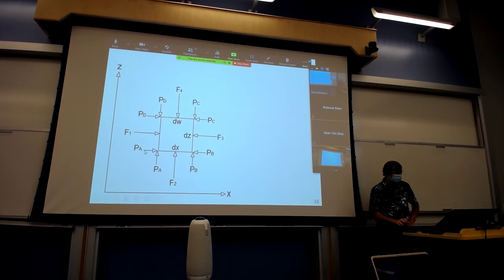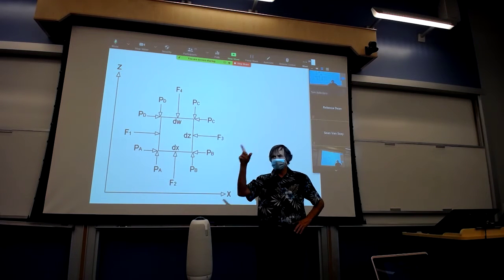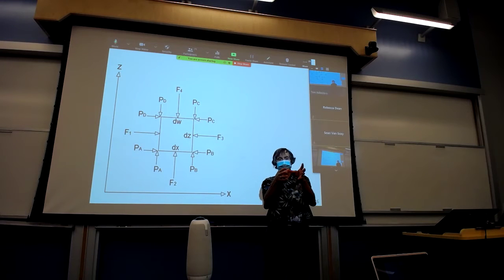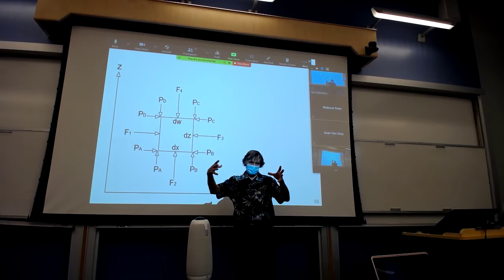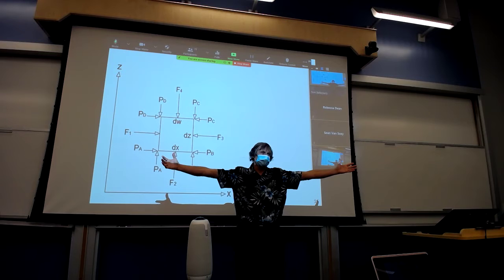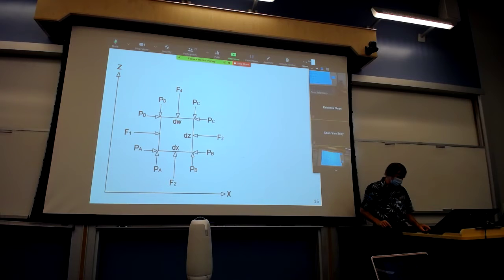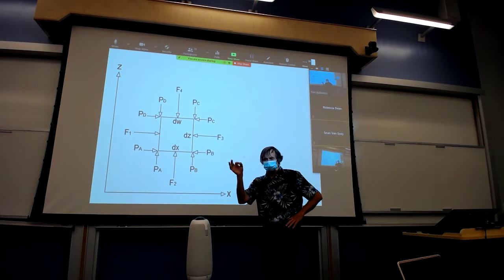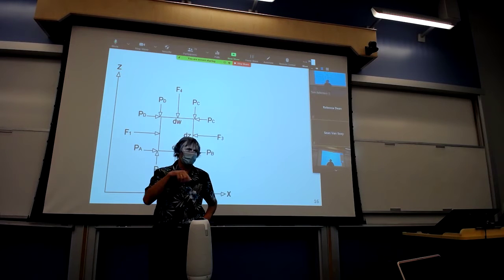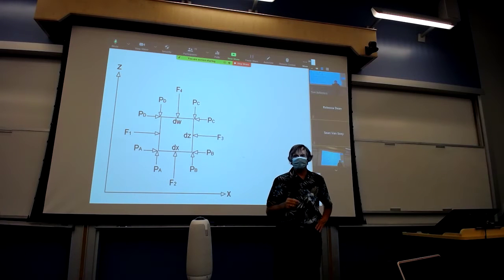Then in this little cube, now a 2D element, we assumed that pressure varied over the outside of this. Again, that represents the fact that we took this little cube and removed it from the fluid, and these pressures acting on the outside represent the rest of the fluid that's really out there. We assumed that pressure was varying as you move through the system. So if we moved from the lower left hand corner, A, to B, we had a change in pressure from PA to PB. Pressure is a scalar quantity. That means that it operates the same in all directions at a point. When we integrate pressure over an area, we get a vector, and that's a force.